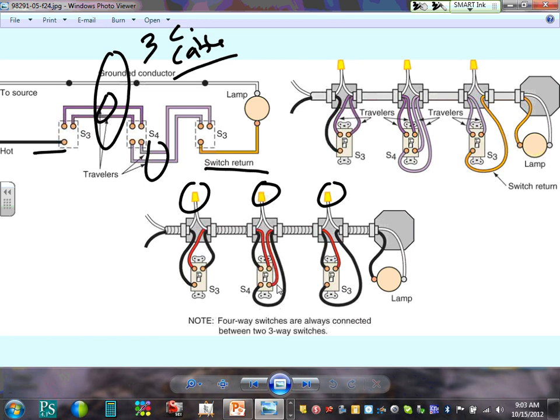So what's the theory behind the neutral only with cable? Because if you change this one to an occupancy sensor, you can always pull in a neutral. Oh, yeah, for conduits, yeah. In conduits, you don't have to provide a neutral. Because in conduits, if you need a neutral, you pull one, hopefully you have enough room to pull a neutral. In a cable, it's hard to pull a neutral after the cable is there. It's not impossible, but you have to rewire the system.